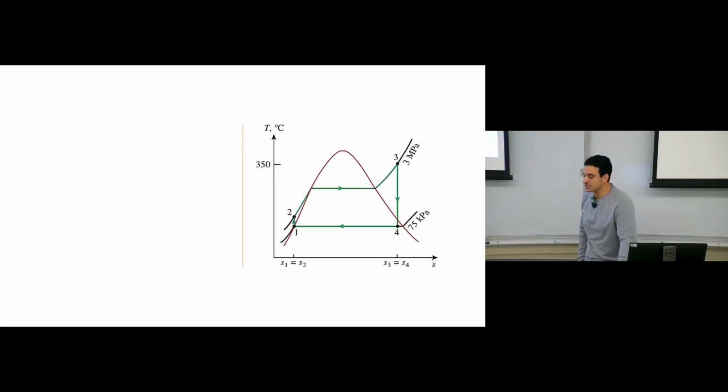What is this reheat Rankine cycle? This is the TS diagram for Rankine cycle. Clear? We have 4 points: 1, 2 for the pump, 2, 3 for the boiler, 3, 4 turbine, 4, 1 the condenser. So let me write these names. So this one, what is happening inside the pump? 2, 3, this represents the changes happening inside the boiler. 3, 4, this represents what is happening inside the turbine. And 4, 1, the last one, this is what is happening inside the condenser.